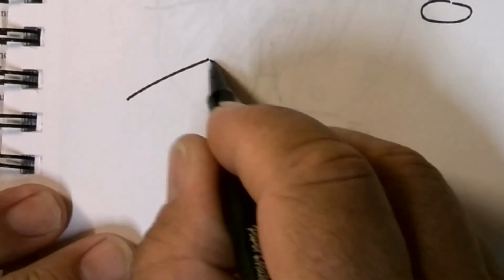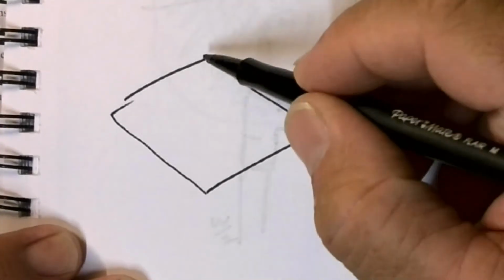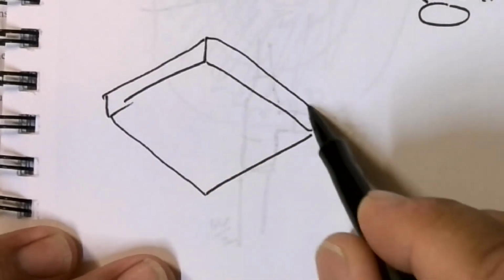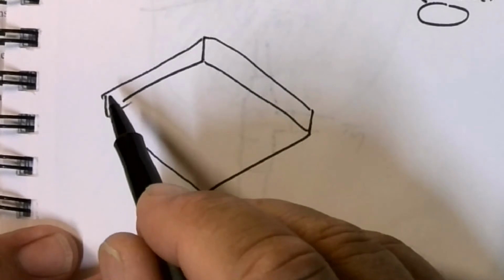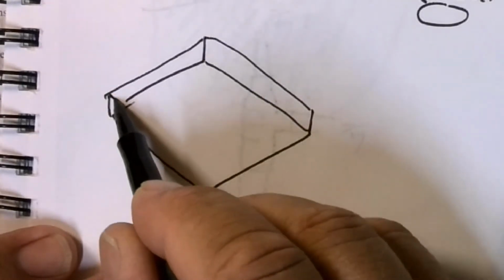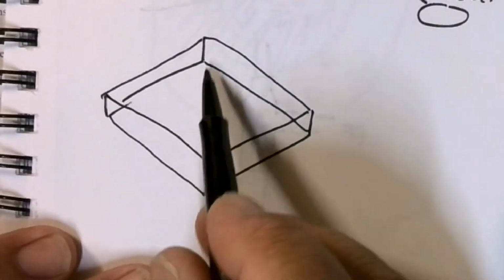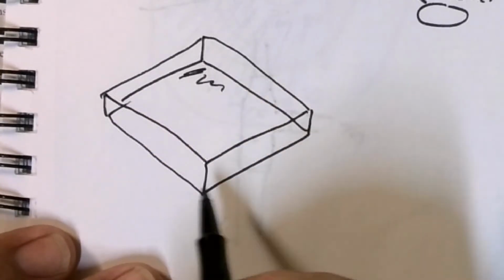So the "such a manner" part is, here we have a rooftop, right? You throw a parapet wall up on this bad boy, and this parapet wall now collects water, so water can collect in here. So you need to open up the side.